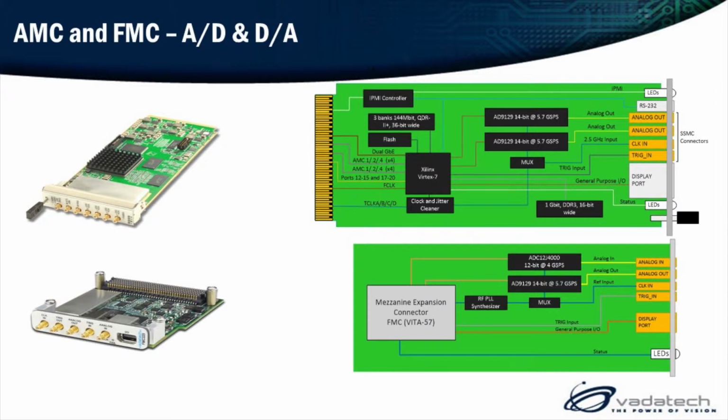This is very nice as you could have the dirty clock across the backplane, have it run through the PLL on the jitter cleaner, ramp up the speed much higher so that the jitter really just gets minimized. It just becomes a blip on the scope, and you run it back out for a clean signal.